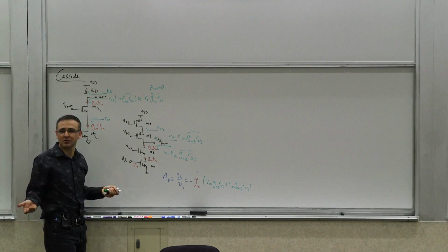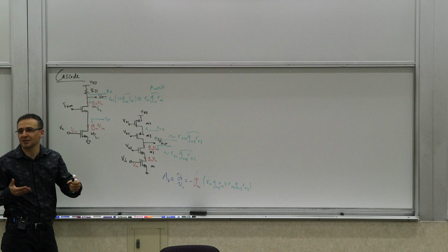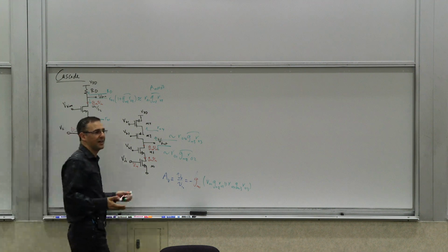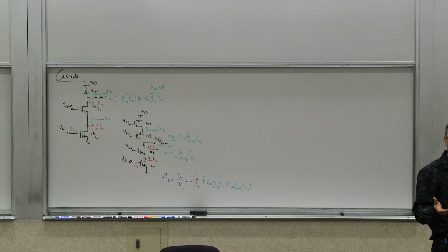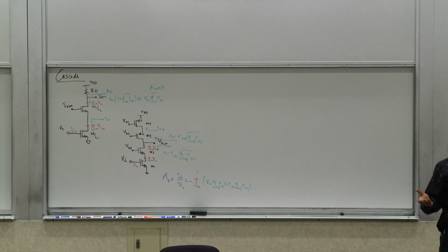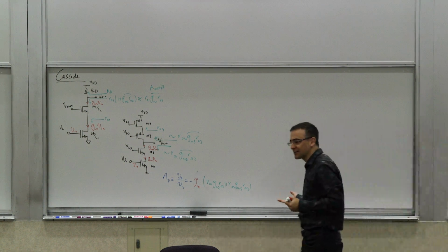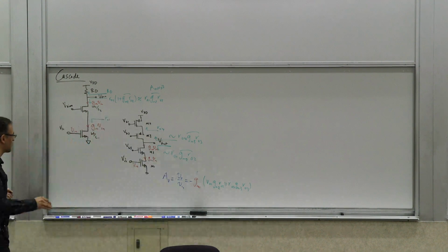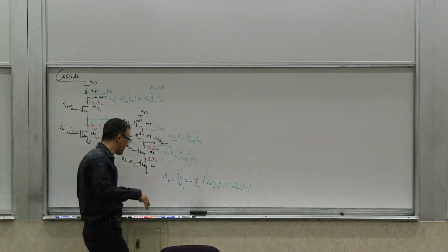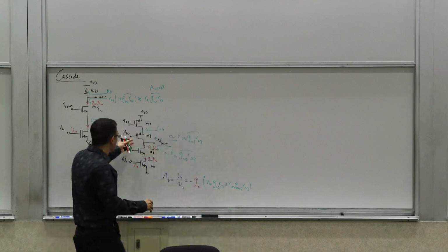There are other resistances you're not modeling, the leakage currents of the diodes and things of that sort. So don't get carried away with this. But you will see sometimes triple cascodes in MOSFETs. I don't think I've seen many practical circuits with quad cascodes, but just triple cascode I've seen. And there may be cases where people use quad cascode. But anyway, that doesn't matter.